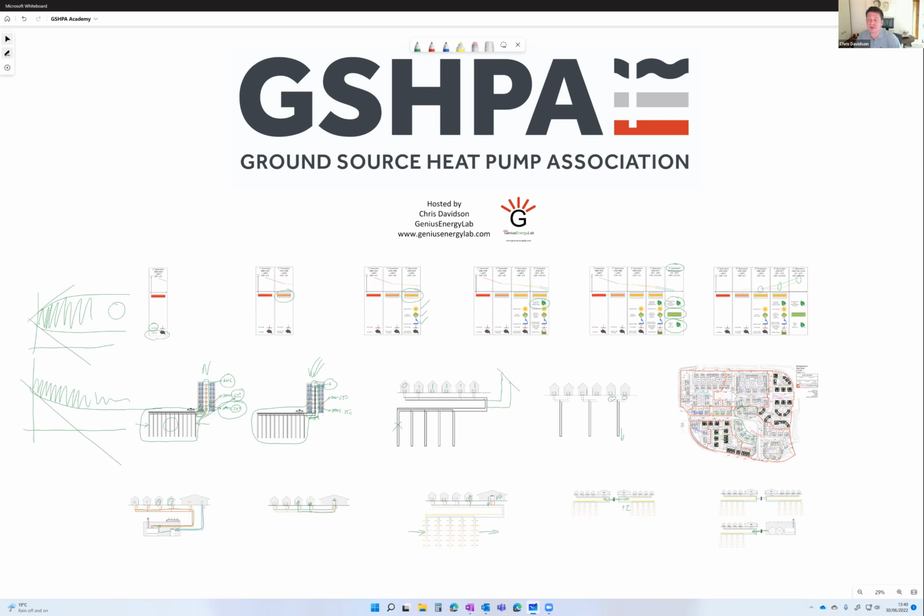But there are a number of commercially available packages for ground loop design, which will include, to some degree, the hydraulics of those systems. The two packages we use at Genius Energy Lab would be GLD by Gaia Geothermal, and the other one would be EED, Earth Energy Designer by Blocon. It's a Swedish package. They have their strengths and weaknesses. Personally, I use GLD more because it's got an accurate heat pump model built into it, and I think that's quite important for the designs.